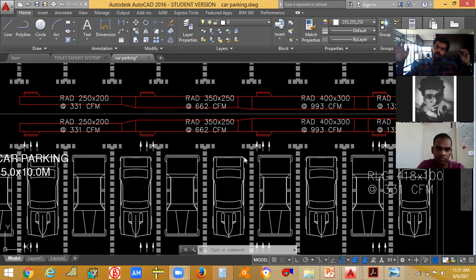Yeah, if all the fans work together, the duct size will be sufficient for the floor. That will be sufficient, but we will be designing with minimum 6 and will give 6 to 8 or 8 to 10, like that. ACH might be minimum only 6. In the normal car park, we will be giving 6, but sometimes we might design with even 10 or something like that.